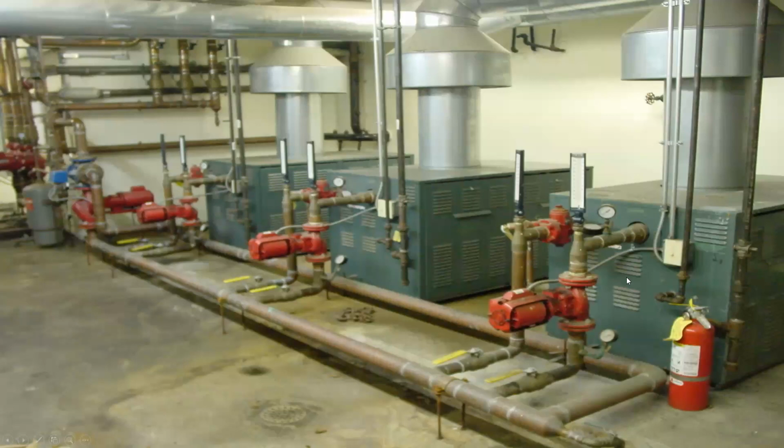You just have these two pipes, a supply manifold and a return manifold, each with its own pump and check valve, instead of doing this whole, because what you've done is you've added this extra kind of loop pump that in this case here happens to be feeding a four-way valve. But yeah, there'd be an easy way to fix that.